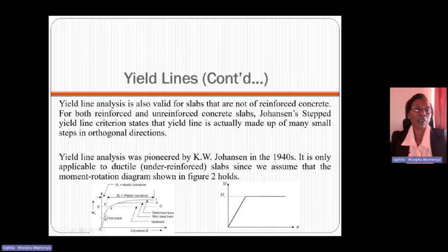Then if you have a curve that goes beyond F and then a horizontal line, that is the characterization for mild steel. The first one was deformed bars. Deformed bars undergo that kind of a curvature. The mild steel undergoes elastic, then there's an elastic limit, and then you undergo a plateau, a plastic plateau like that.